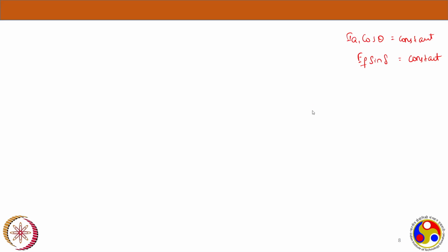So let's draw a phasor diagram for the same. This is my V axis. I will always take capital V as a reference because it's the bus voltage and it's easy to analyze from that point. So this is V, and EF is now V minus jIA XS.